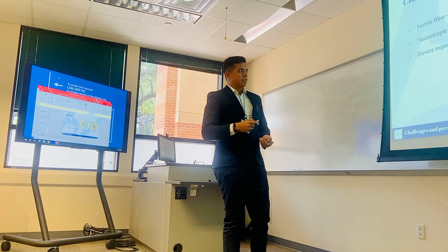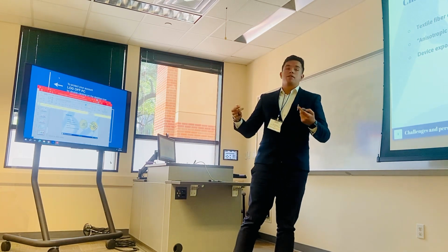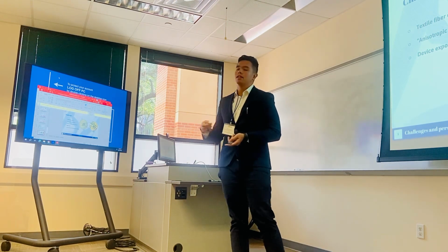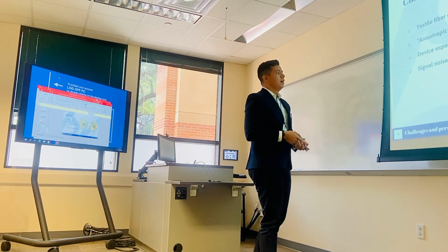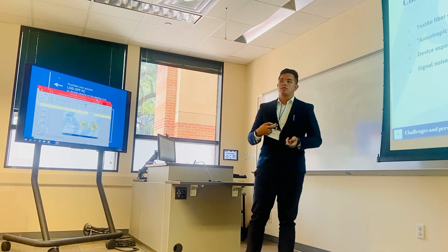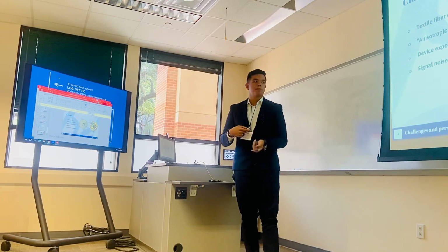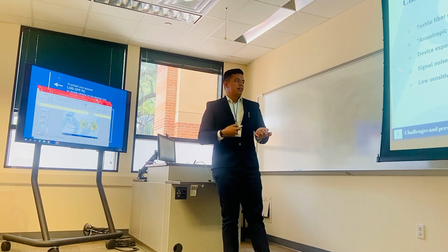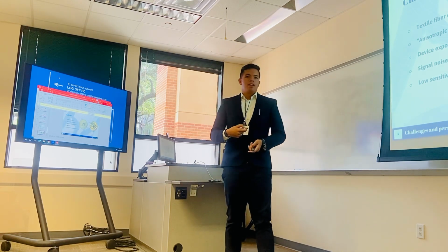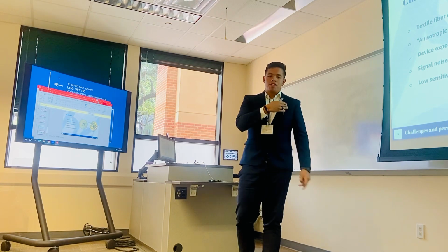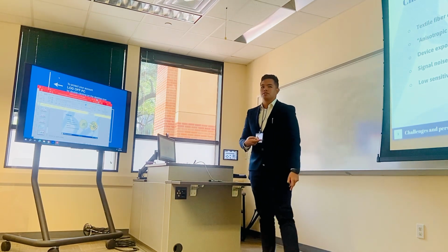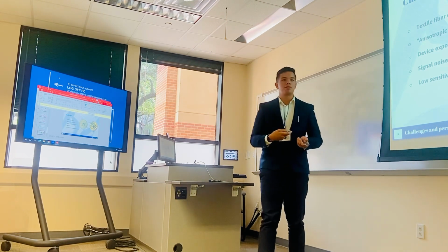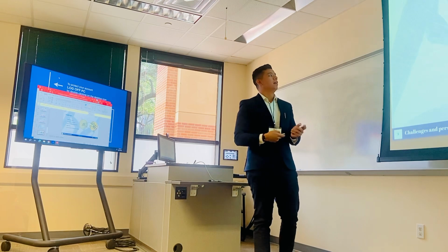Another one is the device's exposure to the environment. A lot of external materials can get in here if the material is not protected, and this can affect the overall performance of it. Signal-to-noise ratio, as I mentioned, is still quite inefficient, but what we did here is pretty much a proof of concept. There is also a low sensitivity to temperature changes. As you saw, we increased the temperature up to 50 degrees Celsius, which is way above our average body temperature. So it's not as sensitive as we want it to be still.